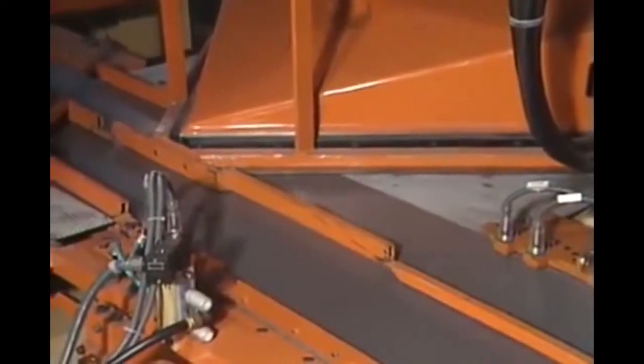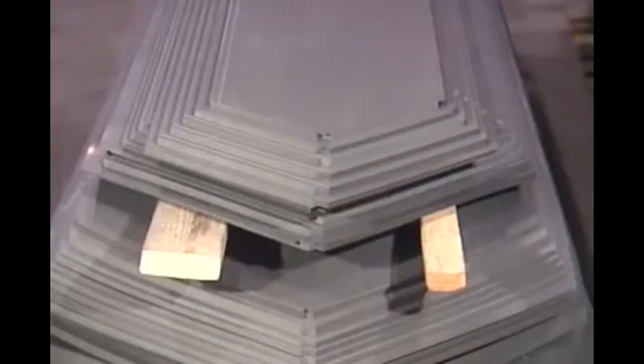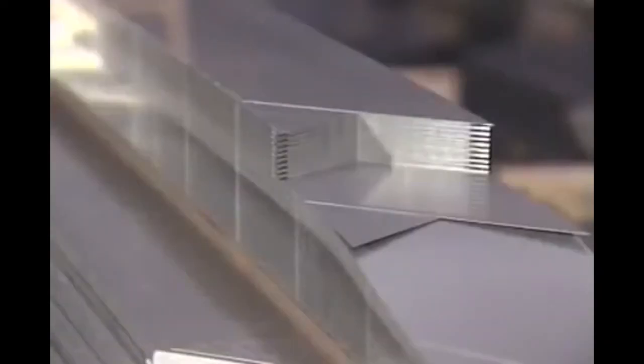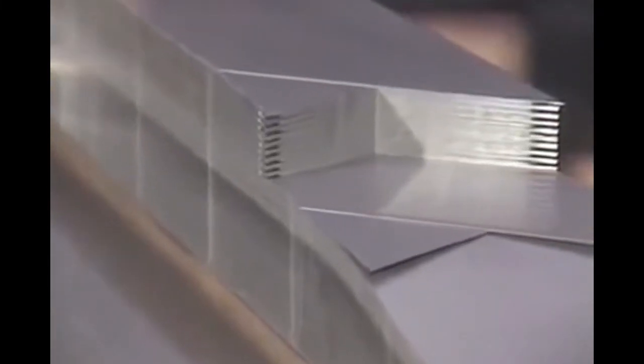Indeed, care and precision are vital throughout this stage of construction, since the core is critical in determining such factors as iron losses, vibration, sound levels and thermal stability. That's why so much care is also taken when stacking the laminations. Expert workmanship ensures that the core's electromagnetic properties are not impaired. The core will later be assembled with the windings to form the transformer's active part.